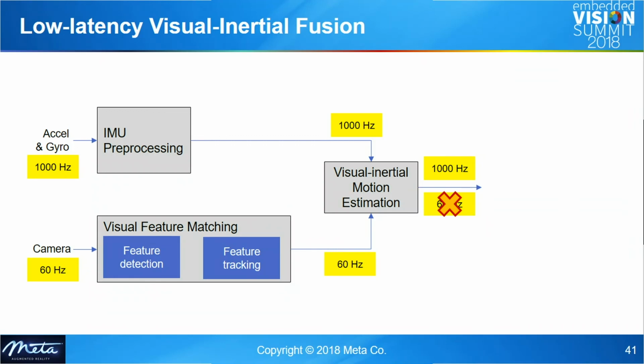I mentioned in the very early part of today's talk that with IMU we can do position estimation for a fraction of a second, and this is what I mean: it's actually enough to do it for a fraction of a second, because then we get the low drift camera-based pose and can correct for whatever drift happened. So this way we can combine the best of both worlds from the IMU and from the camera.